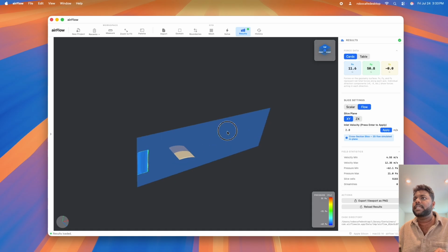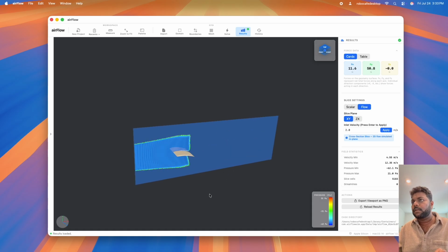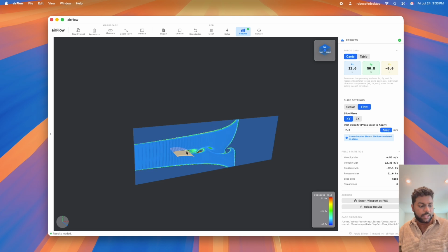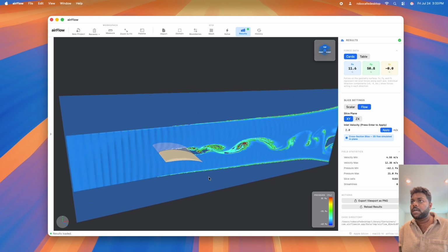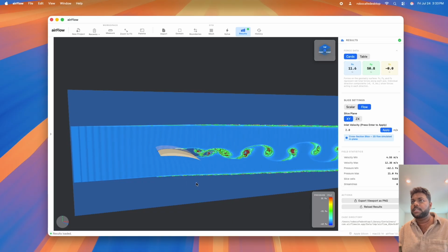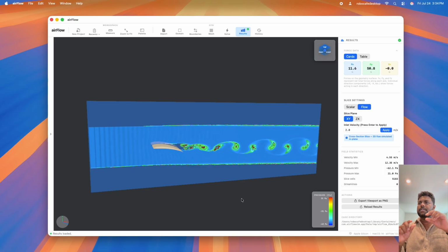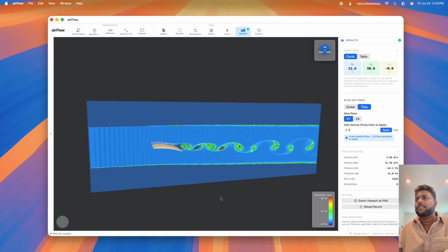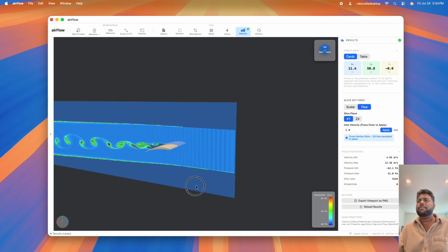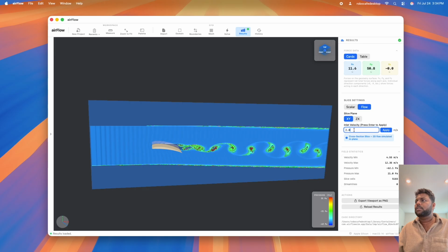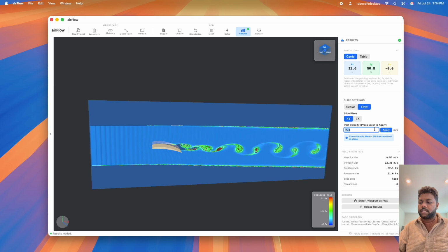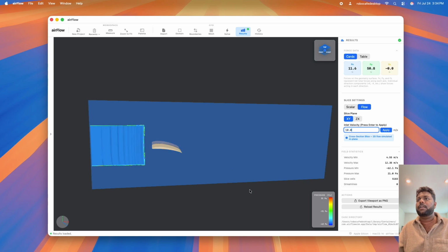And if you want to see the cross-sectional flow, you can clearly see there might be a separation right there because of the angle of attack of the wing, because I believe I gave 10 degrees as angle of attack. The wing is tilted 10 degrees, and we have this angle of attack. And yeah, so there's the flow, and you can rotate it and see from different angles. And you can also change the velocity. Oh, I apologize. The velocity is 2 meters per second. Let's set it for 10 meters per second on the wing.